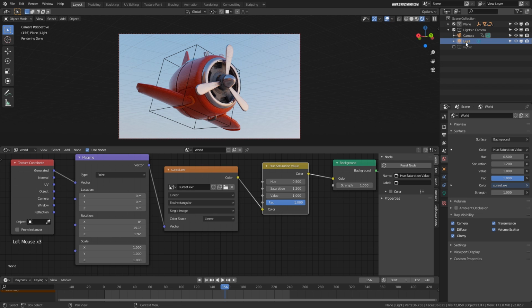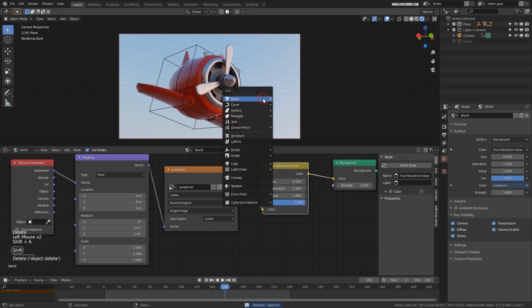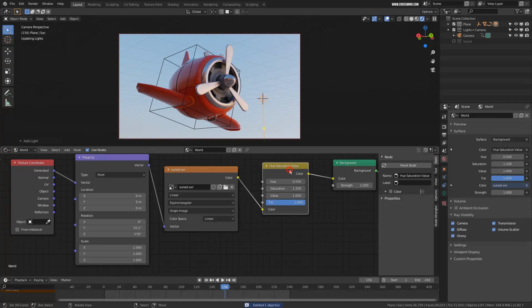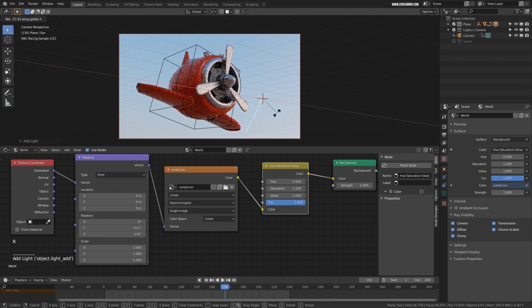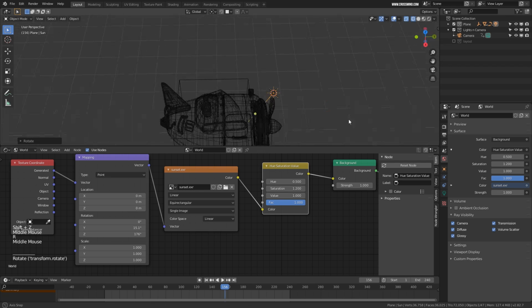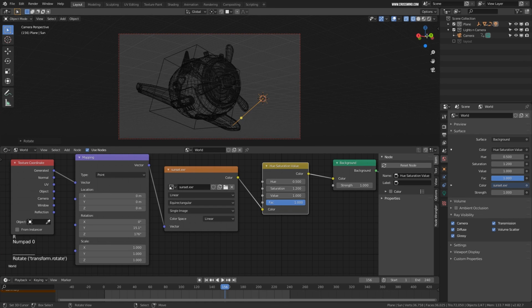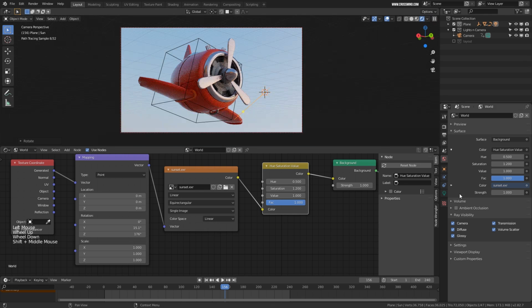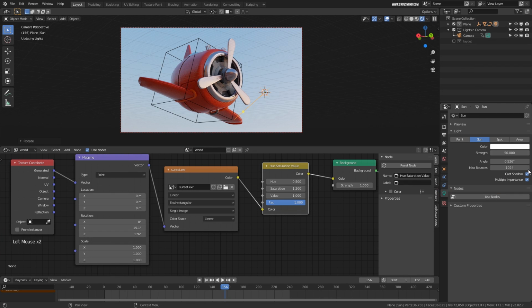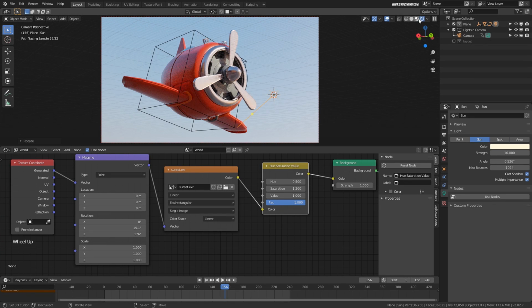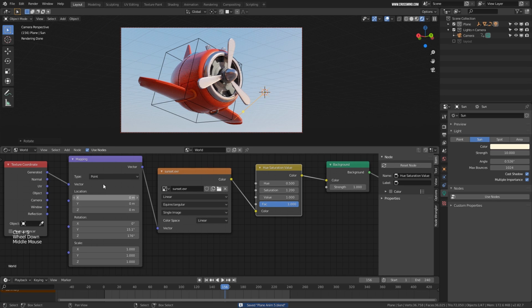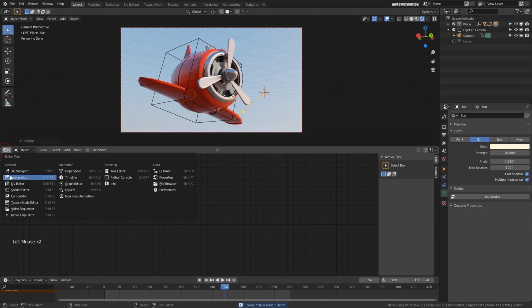Okay, so we have the sky, and we have one light over here, which we created earlier. We don't need it. We can delete this one and bring one more light. It's called sunlight. Okay, and give it some interesting angle. Let's make it something like this. Strength maybe 50 or 20. Okay, give it a slightly warm color like this.